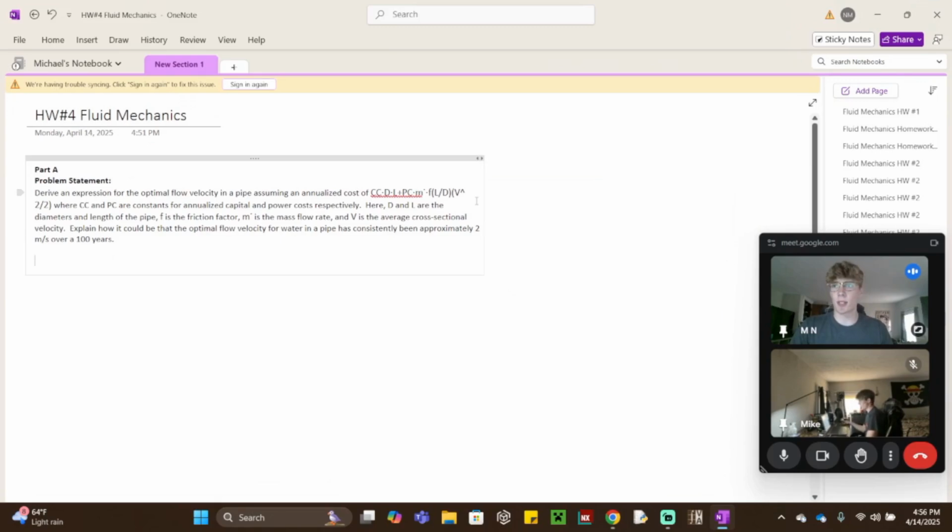Welcome back. This is going to be homework number 4 for fluid mechanics, part A. Part A's problem statement is asking to derive an expression for the optimal flow velocity in a pipe, assuming an annualized cost of Cc times d times L plus Pc times m dot times F L over d times v squared over 2, where Cc and Pc are constants for annualized capital and power cost respectively.